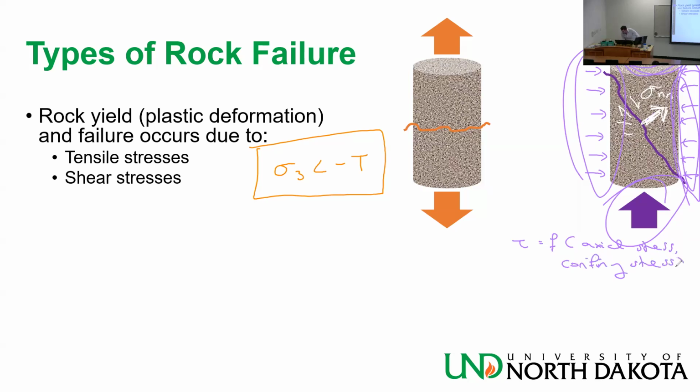When you have the sine here, right? What sine? The angle. Yeah, the angle. Here we have it in the function. It's always around 60 for rocks. Mostly 30 degrees from the main stress. From the stress, we will have a plane with about 30 degrees. And then when you reverse it, you will see the same thing. That's how they identify the stress regime in the field.